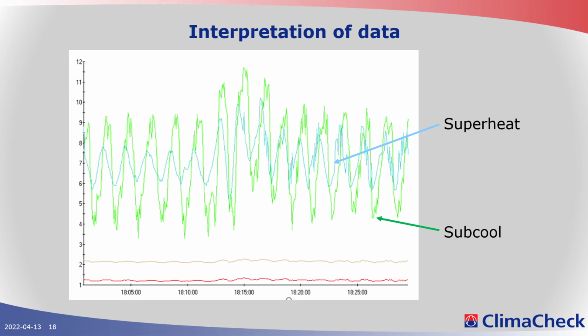But typically, in most systems, if you can avoid a receiver and instead have a bigger condenser, you have useful surface in the condenser, improving your performance, which is much more cost effective than the receiver. So there are, of course, systems where you have a large number of evaporators that can be turned off totally. You have to be able to buffer more than what you can do in your condenser. So in direct evaporation systems, a refrigerant receiver might be required.